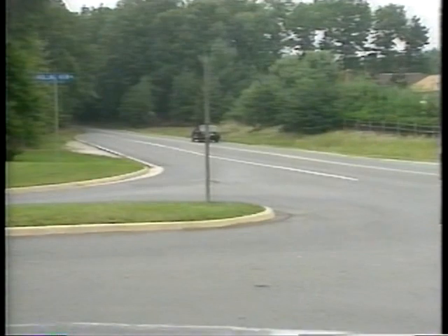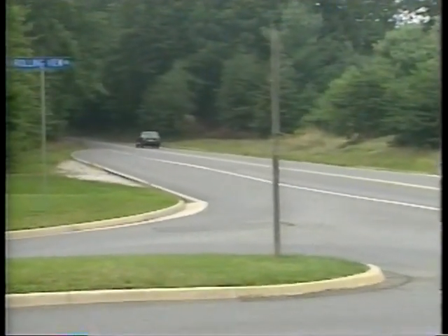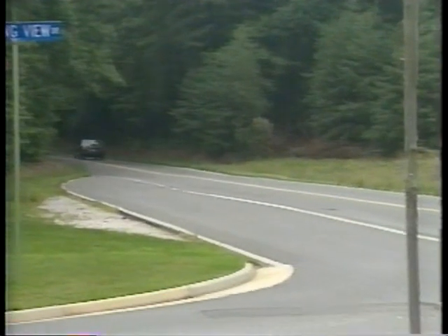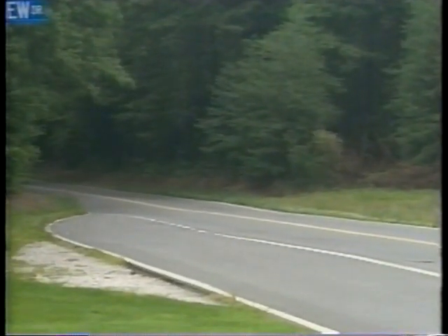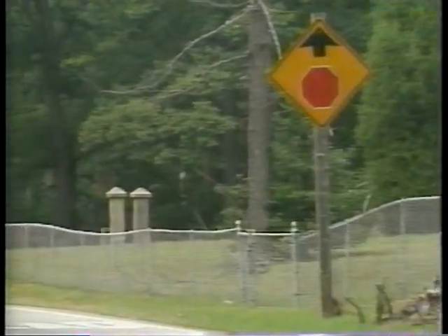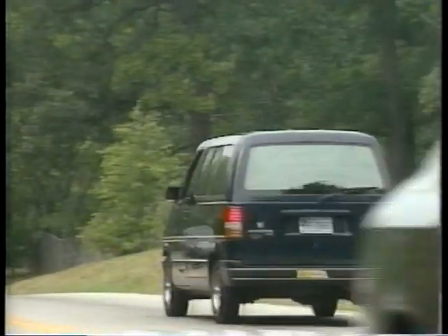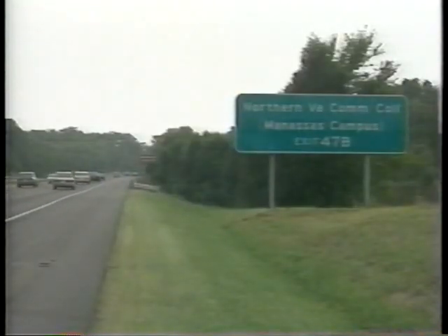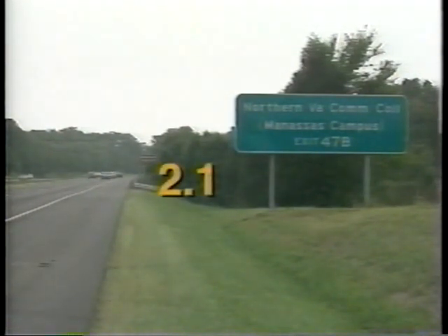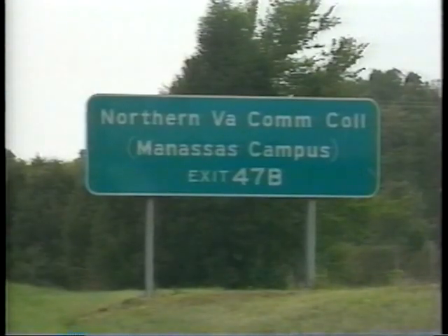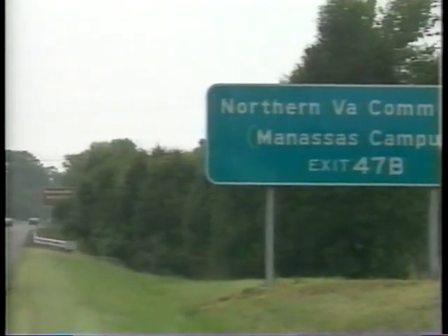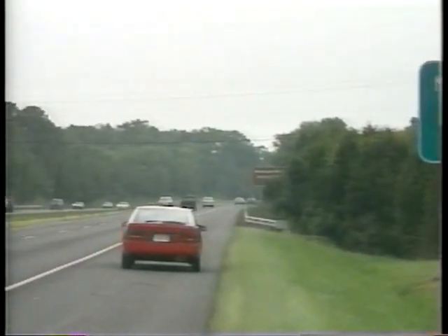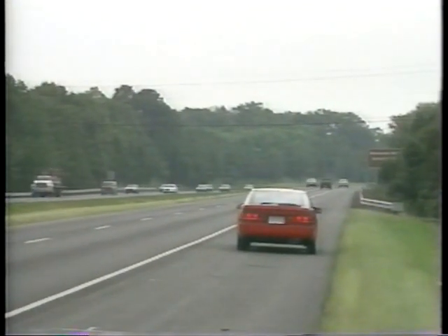At rural intersections, in addition to the stop and yield signs, there may be a need for stop, yield, and signal ahead signs. These signs are used when the stop sign cannot be seen from enough distance for the driver to stop safely. On a freeway, all guide signs beside the road should be at least 2.1 meters above the pavement. There is no rigid criteria for lateral placement, but signs should not be closer than 5.2 meters from the edge of a surface suitable for normal or emergency use by vehicles.